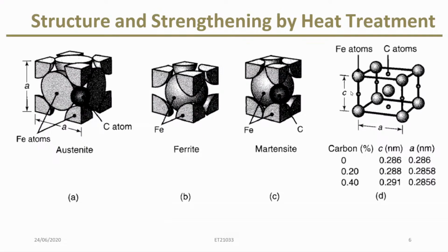The austenite is not our final strengthening stage. It is the starting canvas, and its composition and grain size set the ceiling for the properties we will obtain. In the annealing or normalizing route, slow cooling lets carbon diffuse and form layered pearlite. Pearlite means ferrite plus cementite.